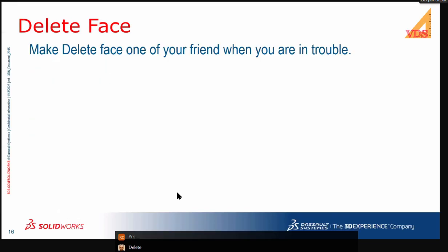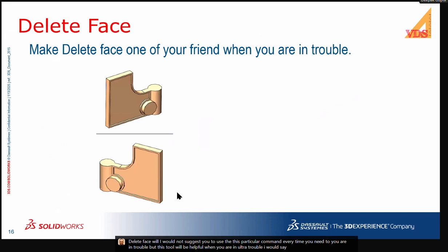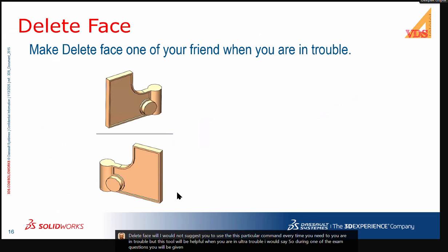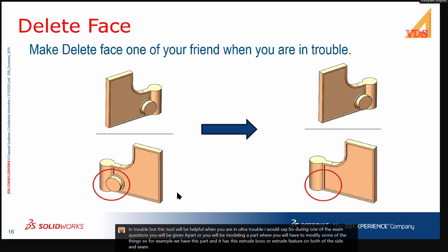Delete face. Well, I would not suggest you to use this particular command every time you are in trouble, but this tool will be helpful when you are in ultra trouble, I would say. During one of the exam questions, you will be given a part, or you will be modeling a part where you will have to modify some of the things. For example, we have this part and it has this extrude boss, the extrude feature on both of the sides, and the exam may require you to remove it from just one side while keeping the design intent intact.